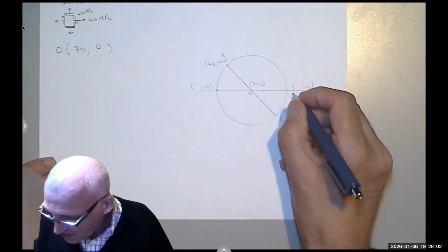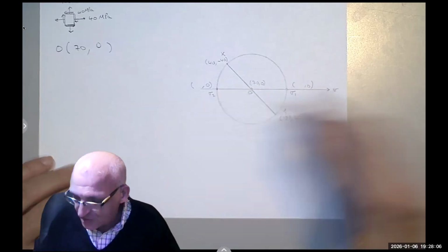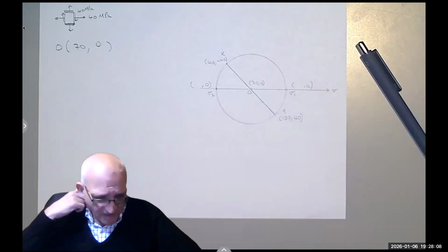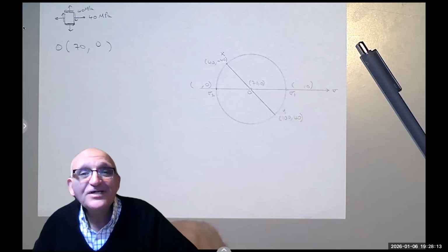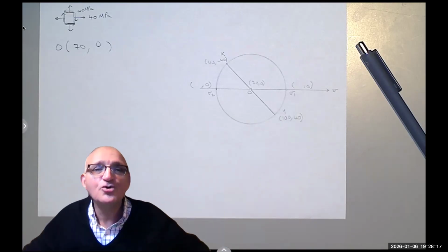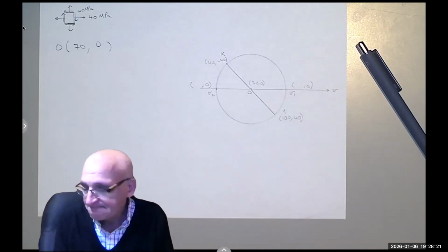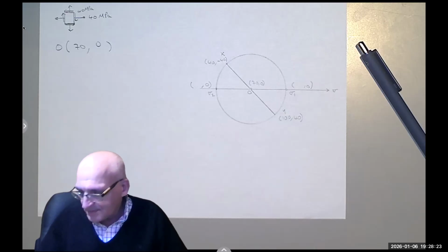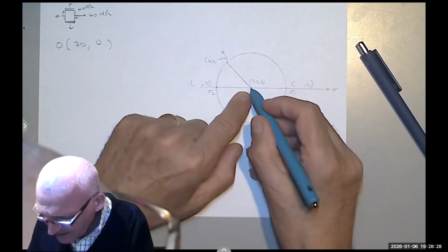We are going to refer to the top one as sigma 1 and the bottom one as sigma 2. Always the bigger is 1. And we call these the principal stresses, the maximum possible normal stress that acts on a body. Okay? So this is a circle, and I know the coordinates of the center.